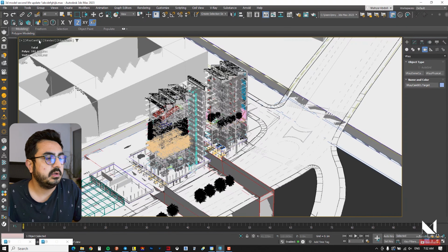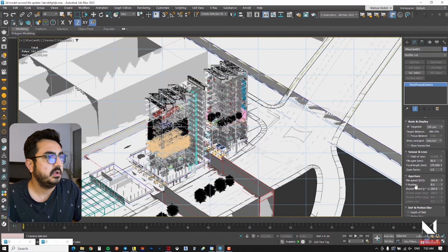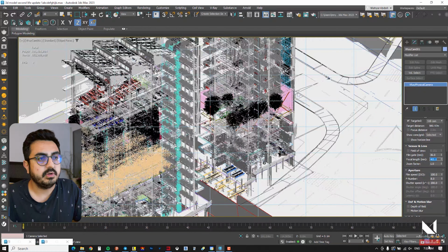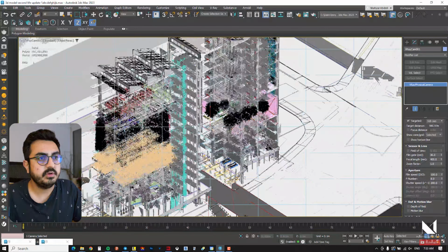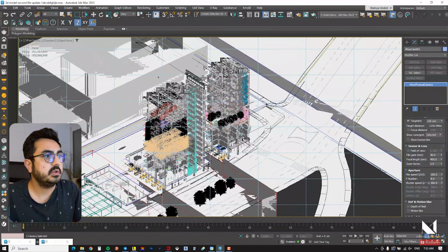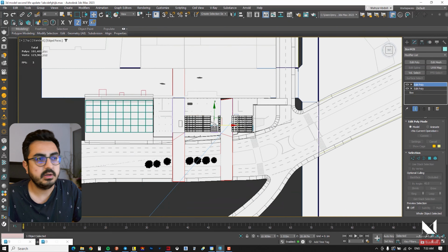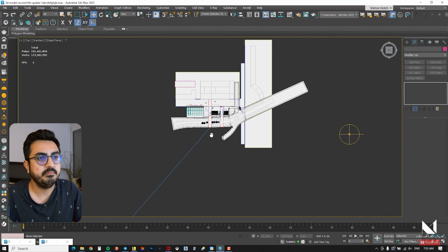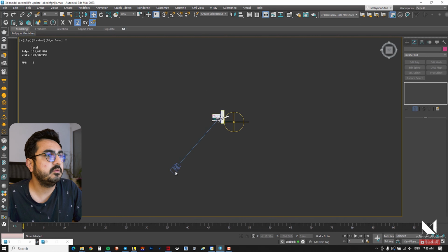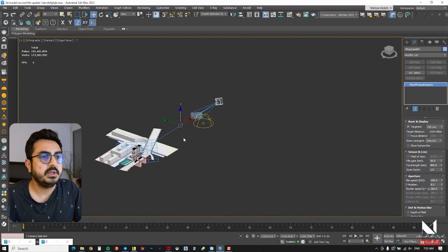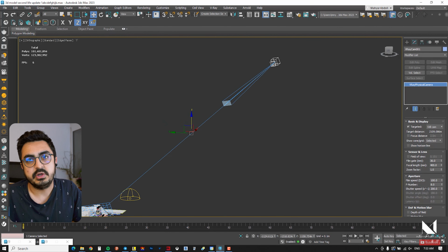So let's say the focal length something like 3000 or 4000. But make sure the camera is positioned farther back and adjust the frame. So this technique almost minimizes the perspective effect to the minimum possible. It's not super precise, but it's a good trick if you're working with V-Ray and focusing on the settings for your axonometric project with V-Ray.